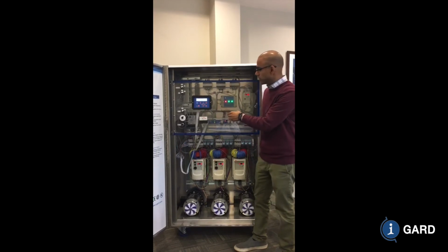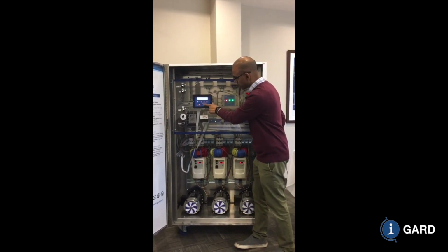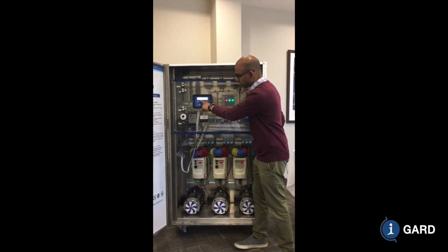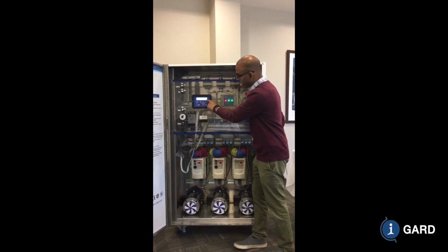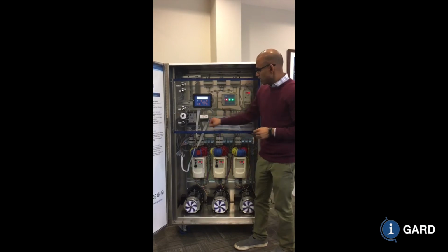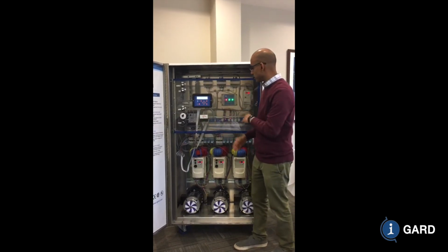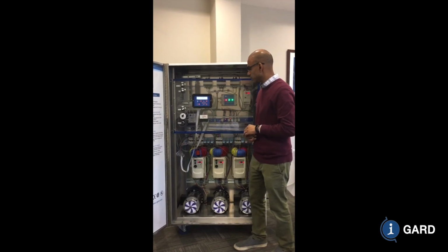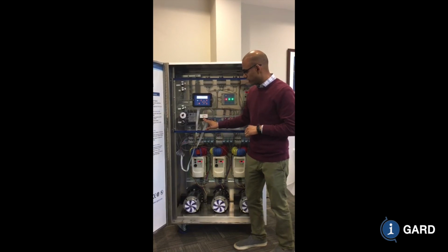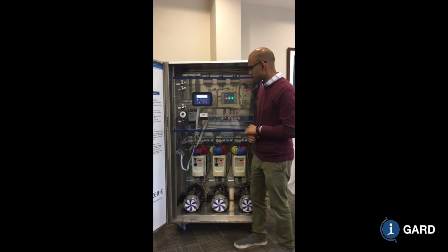Here I can see my feeders. On feeder 3, there's nothing. Feeder 2, nothing. Feeder 1, the double dash means 100%, and it says FLT, fault. So feeder 1 is faulted. This meter is just a meter for this unit, and it shows you the fault current. Notice that the fault current is right now showing that it's at 100% for what we have.